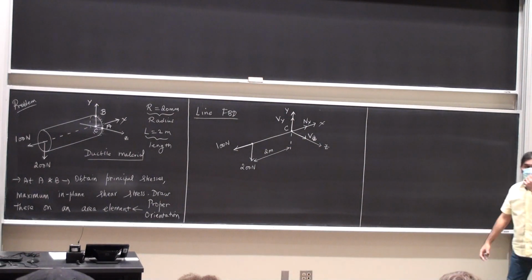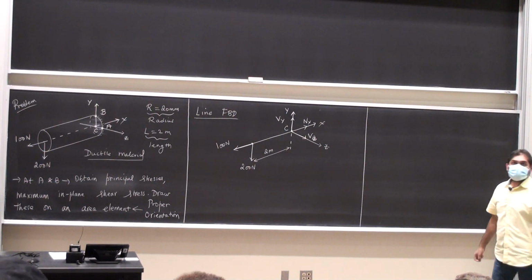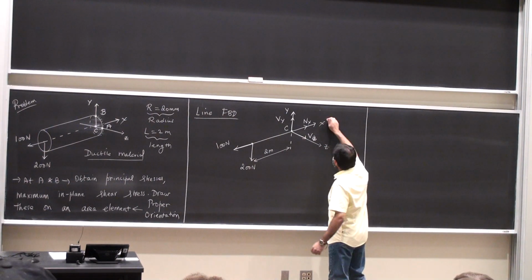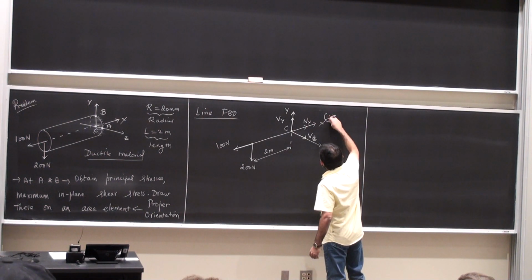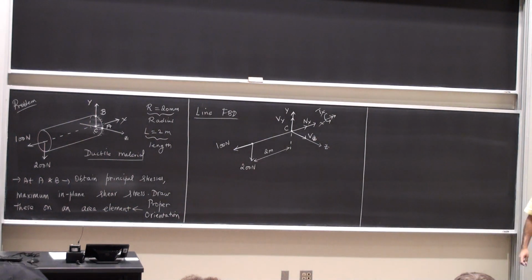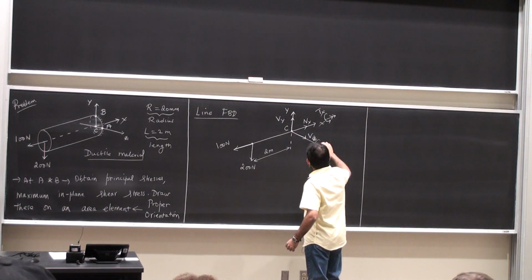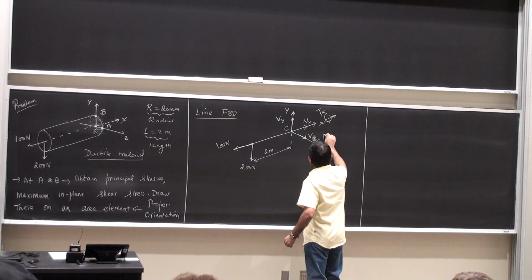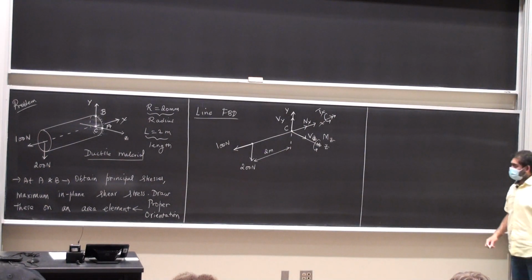Then I'm going to have a reaction torque, which is the internal torque at the fixed end of the shaft along the x-axis, Tx, which is obviously 0 in this problem. Then I'm going to have the bending moments, Mz, and then one more about the y direction.